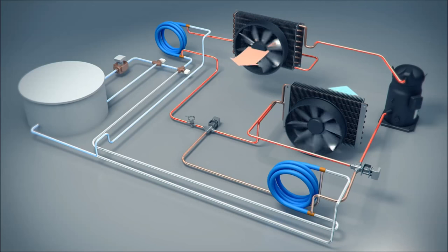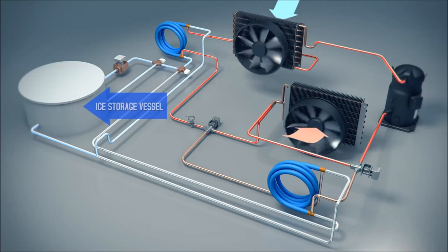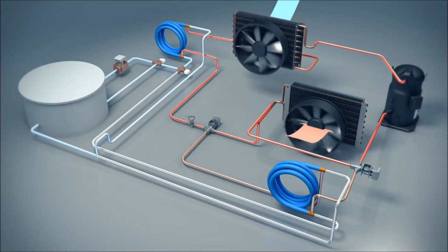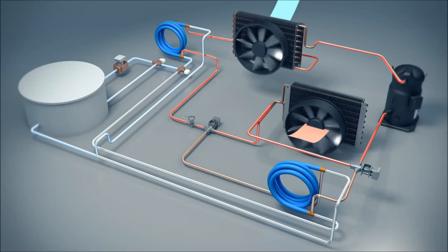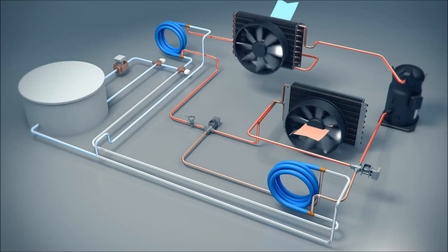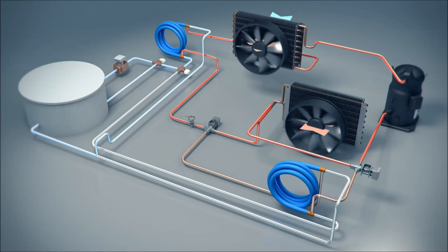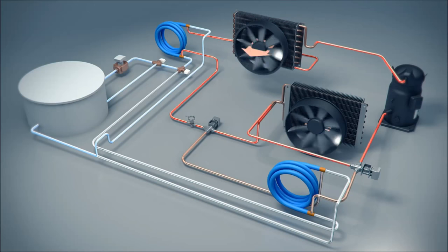The glycol heat transfer medium is then routed to the ice storage vessel. The ice storage vessel is defined as a heat exchanger with an ice-glycol interface. The glycol heat transfer medium is dynamic, whereas the water solution is the stagnant component of the storage vessel. The glycol thereby transfers heat to the solid ice solution, resulting in a phase change. The glycol then leaves the ice storage vessel at a significantly reduced temperature and continues its path through a series